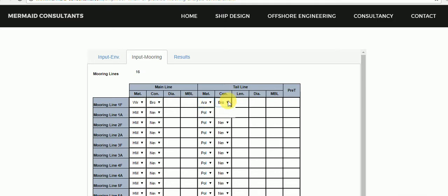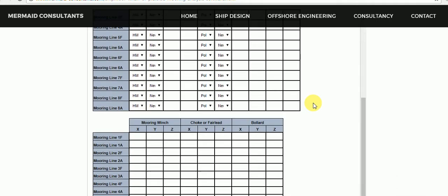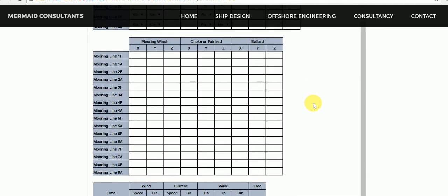Vessel and terminal personnel can train on Shipmoor to learn proper techniques of arranging and tending mooring lines. Advantages and problems of various mooring arrangements can be demonstrated. The time forward feature with tide, draft and trim changes will illustrate how to anticipate line tending and what is the best tending action.